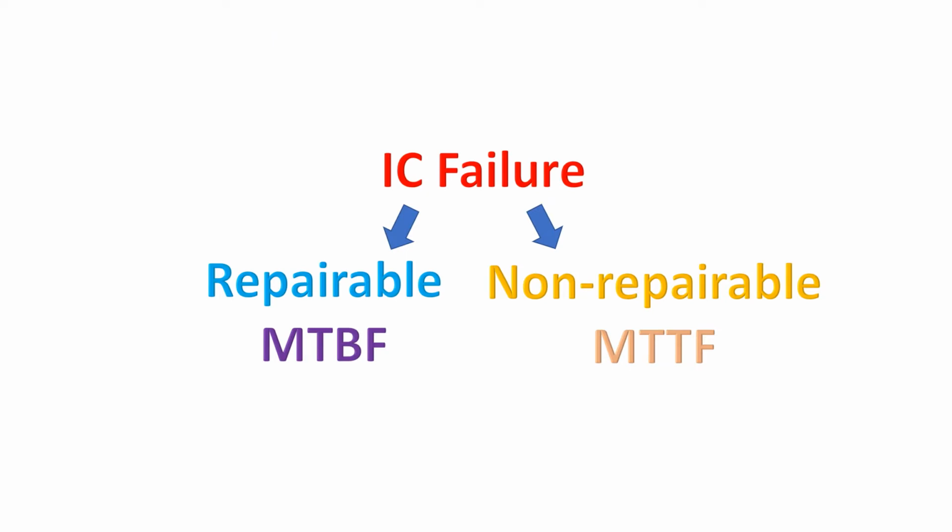IC failures are usually either repairable or non-repairable. The repairable condition is characterized by MTBF, which means mean time between failures. You can usually see them between clock domain crossings or reset domain crossings. However, non-repairable failures are characterized by mean time to failure.